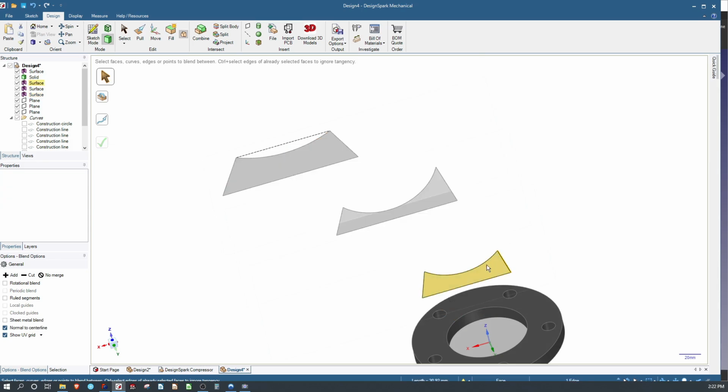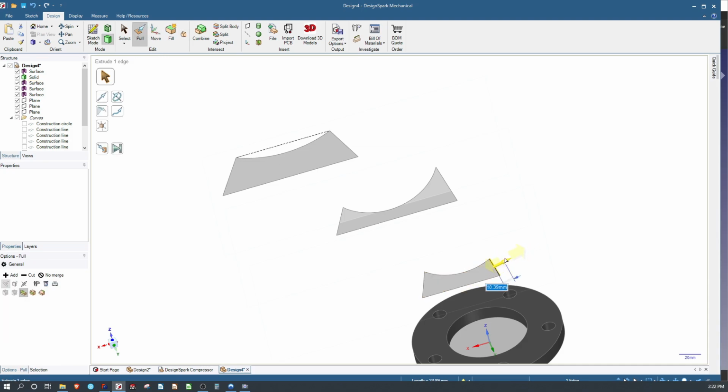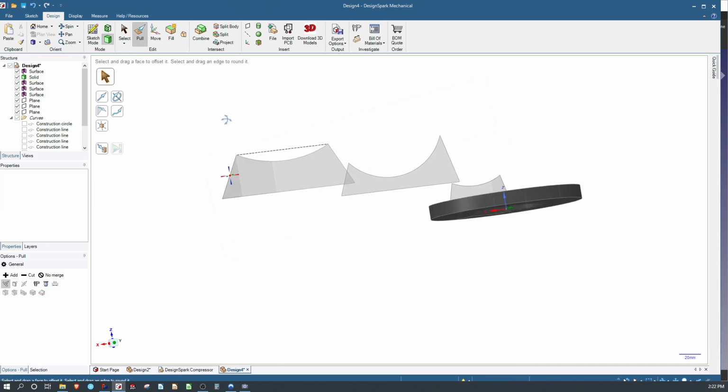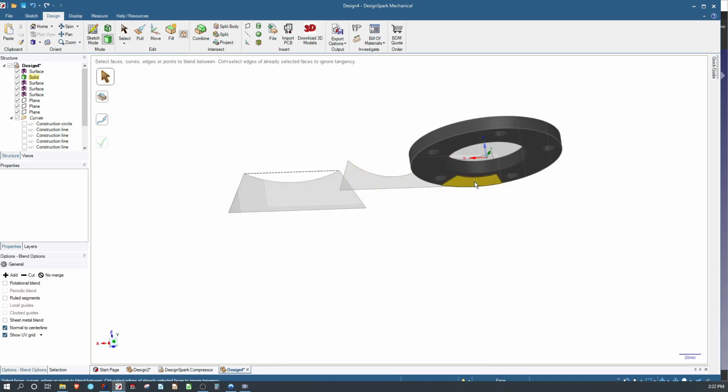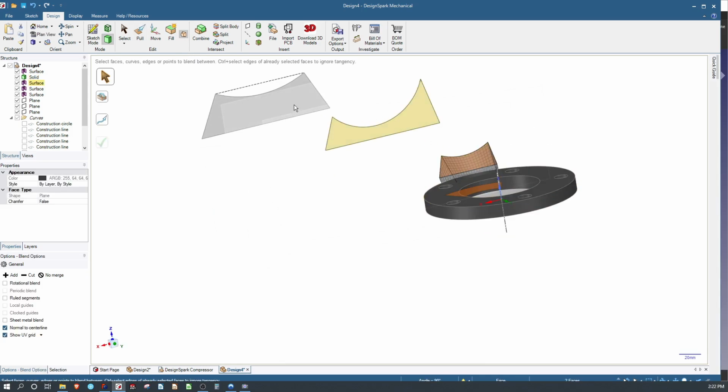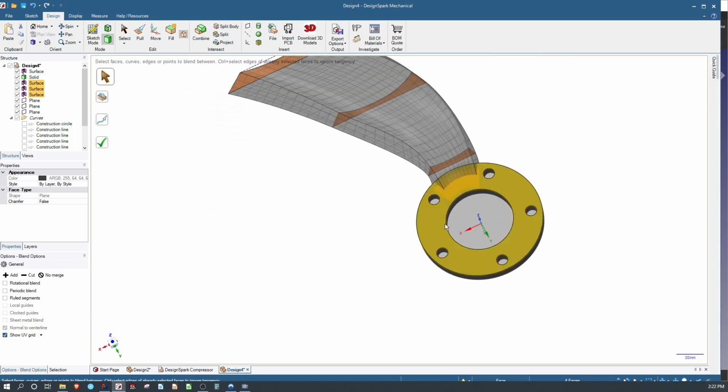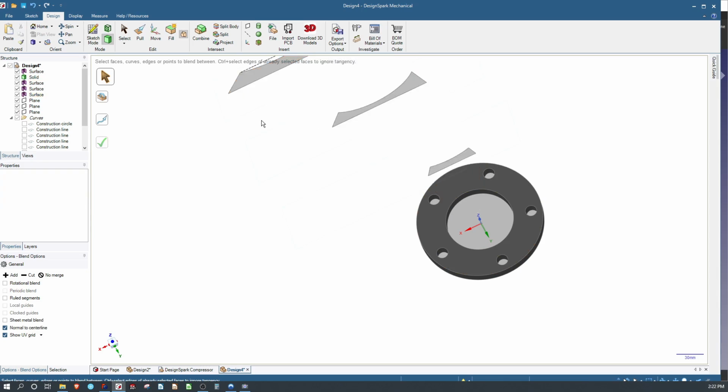And again, I don't have a sketch to be able to adjust this, so we are going on direct editing to do this. Right? If I adjust my profile of this edge and I just bring these edges in, and then I go back to my blend tool, and I'm just kind of going back and forth in my blending preview to see what our spoke is going to look like. I like that better. Let's narrow this up a little bit.